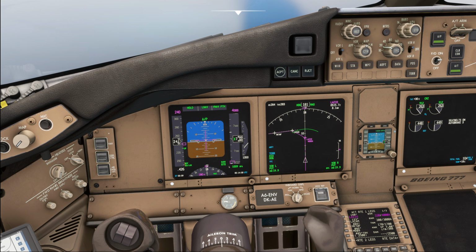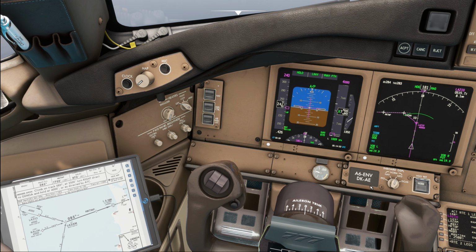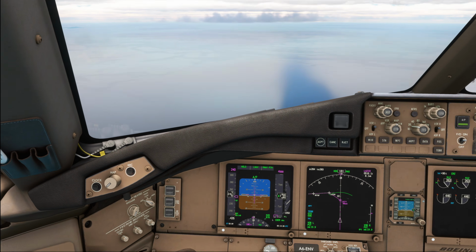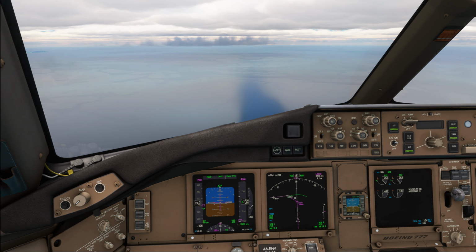And just to give you an idea, if you accidentally select a QNH of, let's say for example, 10 hectopascals less, so for example 1003 instead of 1013, that would mean that you're actually going to arrive at sea level 1 nautical mile prior to the runway. Obstacle clearance is not assured like this, and there have been accidents in the past where aircraft crashed into the terrain just because the altimeter setting was incorrect on a non-precision approach.